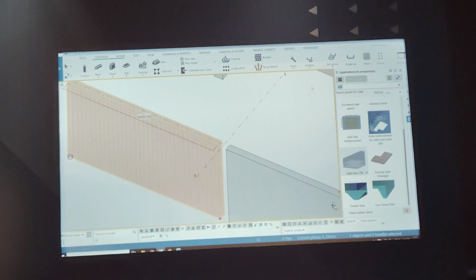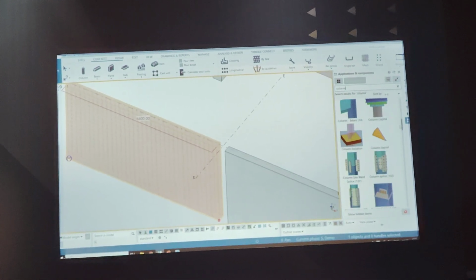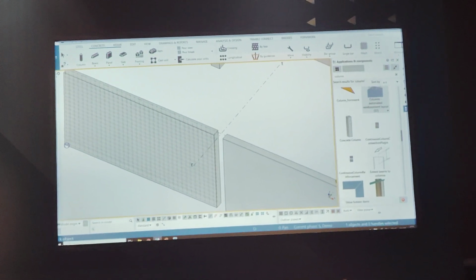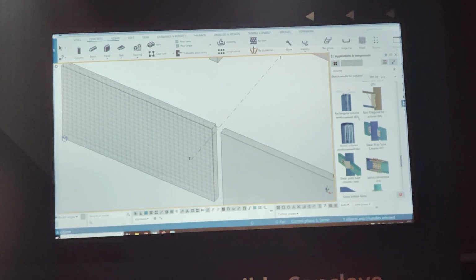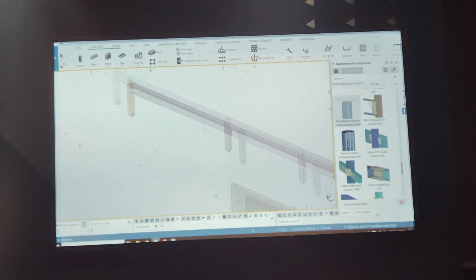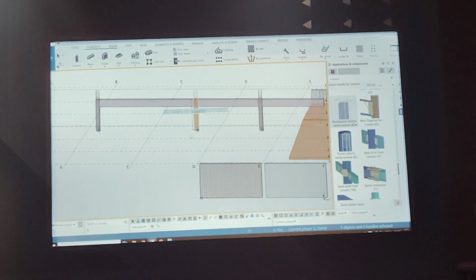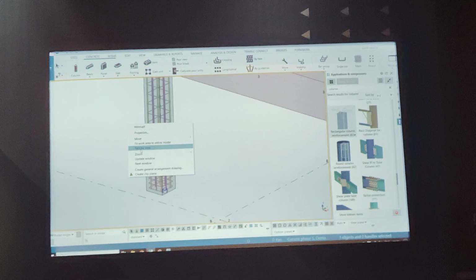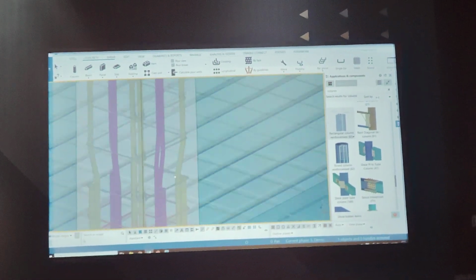I can go and search for column, and you will find a lot of tools for the column reinforcement. So here we have column automatic reinforcement. We have column former and continuous column plugin. There are different options, different representations. You can choose whichever is feasible or according to my requirement. I can add those reinforcement details just through the window selection. Okay, when I just redraw it, you will see it has applied the reinforcement with the crank and the stirrups.